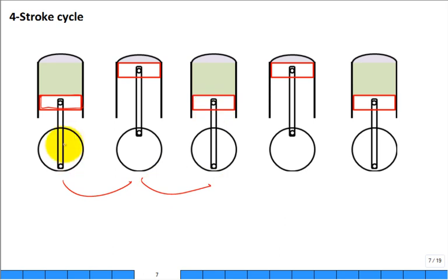Notice that it's connected to this rotating shaft, and this is the offset. And so when the shaft is rotated such that the pin connected to that offset, right here with this connecting rod, is at the top, then after it rotates another 180 degrees, it'll be at the bottom. Then it rotates another 180 degrees, it'll be at the top. That's how you get the linear motion, the reciprocating motion in the cylinder. It's connected to the crank that way.